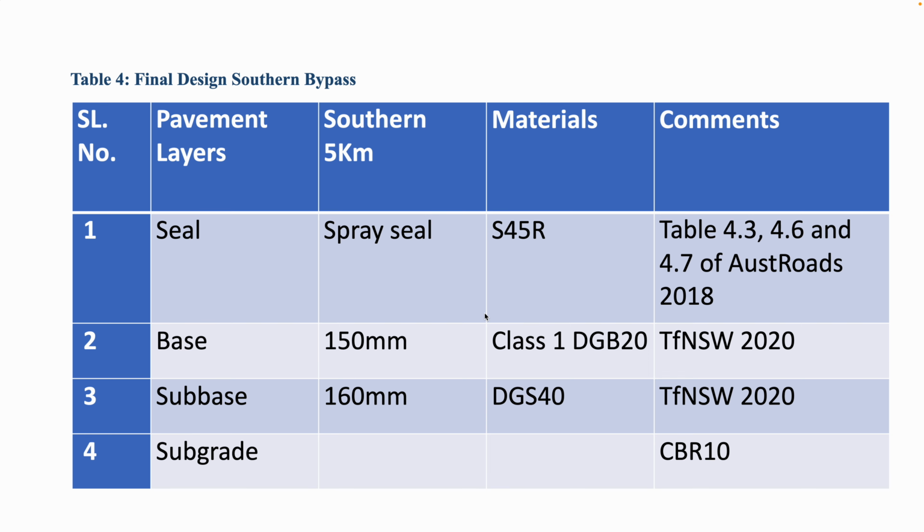Final design of the southern bypass, we can see it's all the same. We'll be using the same material for base and sub-base, which is class 1 DGB20 and DGS40.